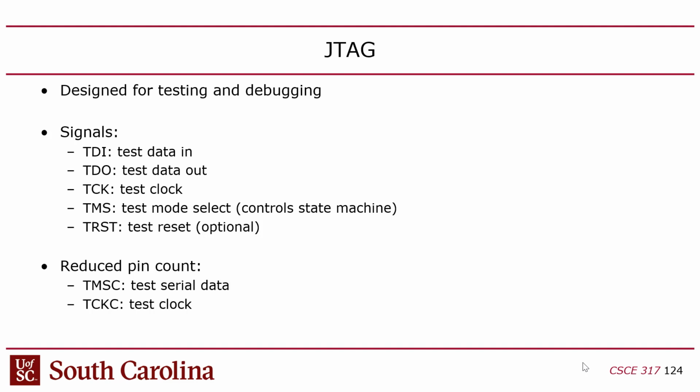That's why they call it BGA. There's not actually balls after it's cooked because the balls melt and they turn into just a solder joint, right? The problem is that once you put the chip on there, you can't see any pins on this thing, right? I mean, you see the FPGA, it looks like this black ceramic package, but you don't see any of the pins, and you can't reach any of the pins with a probe.